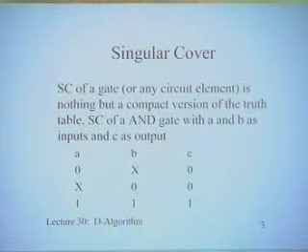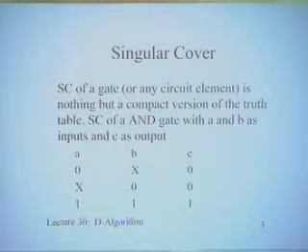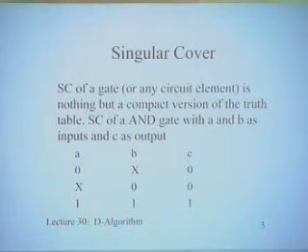Let me tell you one thing, that it's important to realize what's happening. So basically how are we proceeding, from two points of view. What we are doing here is at the gate level, but as I said, you can apply the D algorithm for any other combinational circuit. As long as you know the procedure, you can generate all the other intermediate inputs required, that is the PDCF, PDC and so on that we are going to discuss. Of course for PDCF and PDC for gates you can actually do it even just by basic analysis.